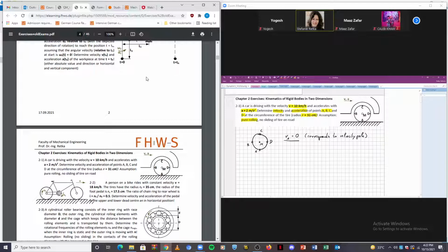So right here, on to our velocities, we know that if our car travels with 10 kilometers per hour, the center of the tire, the axis of the car, travels with 10 kilometers per hour as well. Now, knowing this, we can use the approach for the velocity pole, because now we know that Vm can be described as pure rotation about point A, and this is the radius, the distance from M to A, times angular velocity, exactly, r times omega.